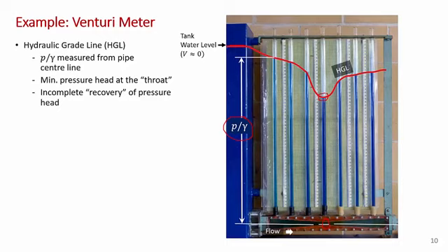I'll also point out something interesting. In contrast to the ideal flow in a Venturi that we talked about earlier, you don't get complete recovery of the pressure head. So the heights of the piezometers for the first and the last piezometer are not the same, even though the cross-sectional areas of the Venturi meter are the same at those locations. This is an indication that you've got some losses in the system, some energy losses. So pressure is decreasing in the downstream direction. You're losing some pressure head because of, well, viscous losses and because of turbulence.